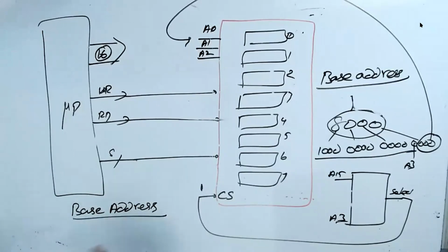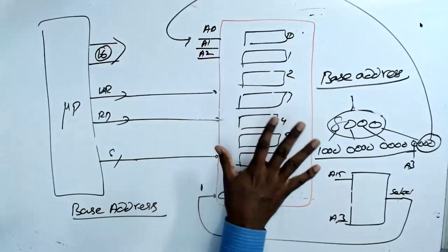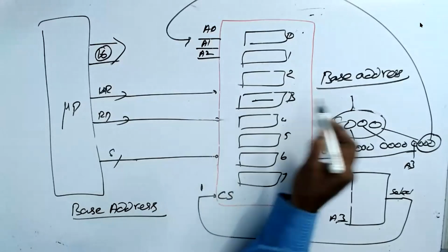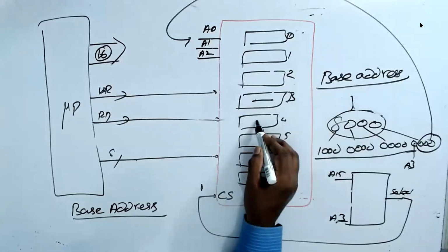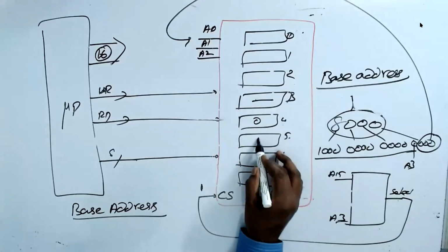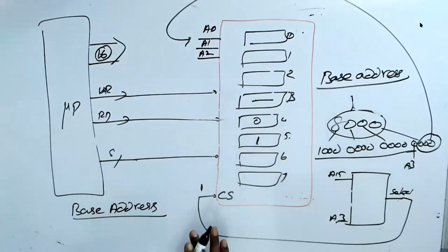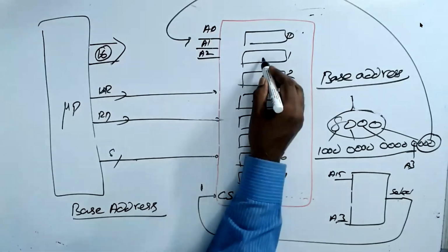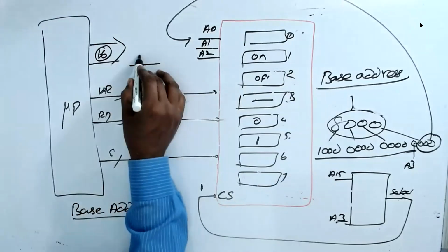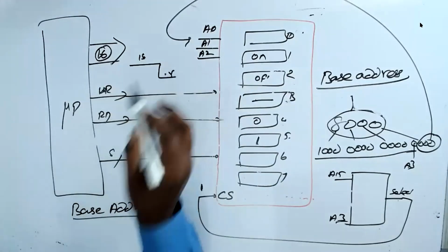And when you want to write to the registers based on the functionality, if the manufacturer tells you that, hey, in 3, if you write, I will blink the LED. And if you write 0 on the 4th one, I will stop the LED. If you put on 5, I will restart the blinking. Understand these things. And this is called on time. This is called off time. For example, I want to on for 1 second, off for 0.5 seconds. I can change it.